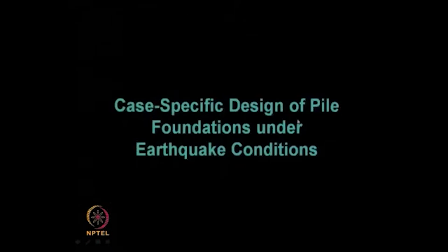So, coming to case specific design for pile foundation under earthquake condition. Why case specific? I have mentioned in the previous lecture, as recommended by Poulos and various other researchers, that for a particular soil location, how much ground amplification, site response and soil behavior are going to affect the pile design, and seismicity need to be considered. That is why case specific design is important.